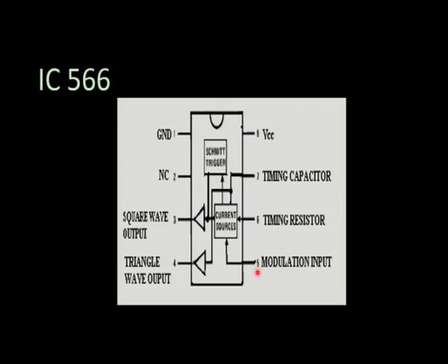Pin number 5 is the modulation input. Pin number 6 is where the timing resistor is connected. Pin number 7 is where the timing capacitor is connected. Pin number 8 is connected to VCC. So, it is an 8 pin IC.